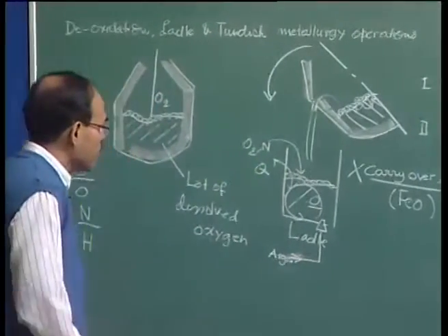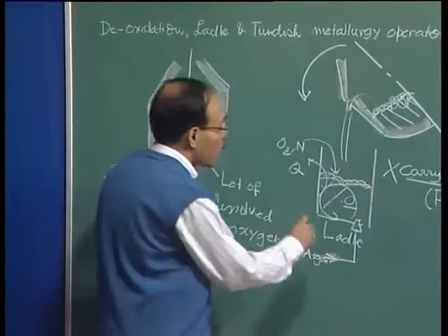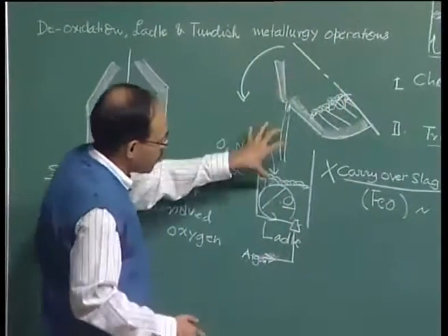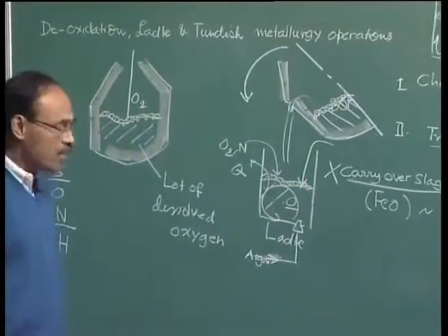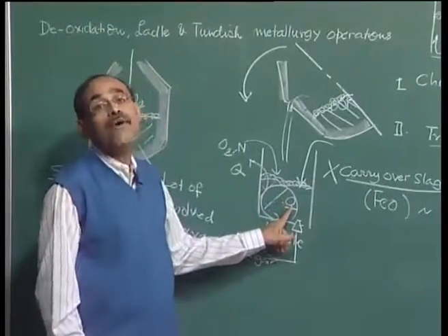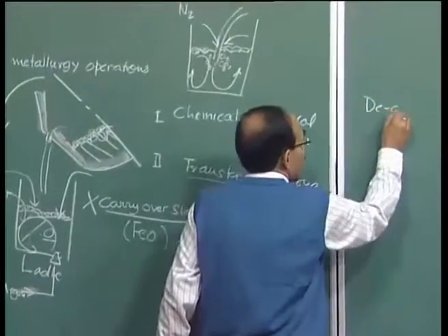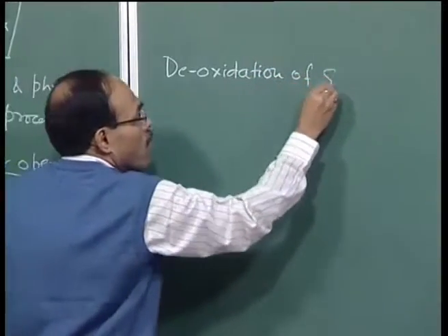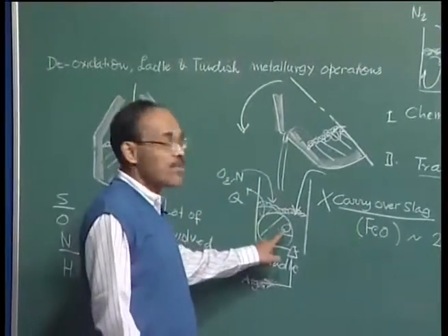We can see that before the material is completely filled, as the basic oxygen furnace is being emptied, we are going to continuously add deoxidizer elements into the steel bath. The first step, as I mentioned, is to drive out this oxygen, and this is called deoxidation of the steel bath. And to deoxidize the steel bath, we basically add elements which have a very high affinity for oxygen.